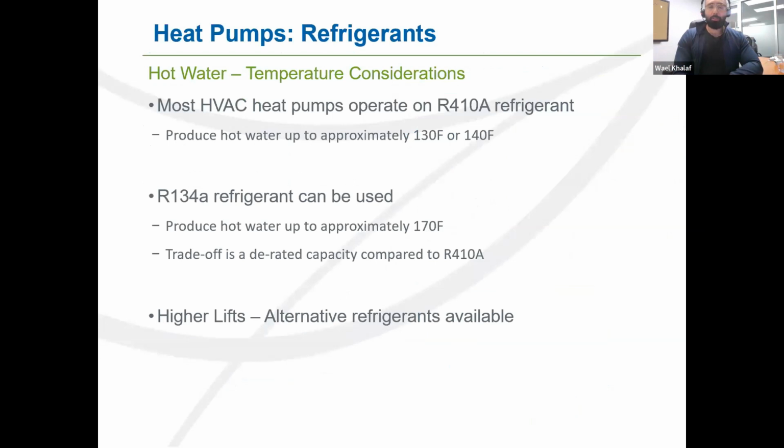So if we look at refrigerants, I could probably spend 3 hours talking about refrigerants and the new refrigerants that are coming out. I just want to talk about what's the most commonly available and the most popular ones we're seeing. Most commercial heat pumps we're seeing today still use HFC refrigerants. That could be R410A or R134A as the most common ones.